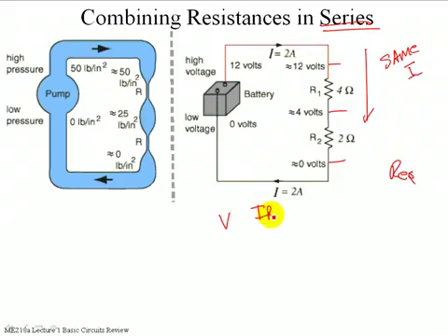So we got IR1. What symbol am I putting between the V and the IR1? Minus. Yes. I start with this much voltage and then I drop voltages across the resistors. So V minus IR1 minus I, the same I, R2 is equal to 0.